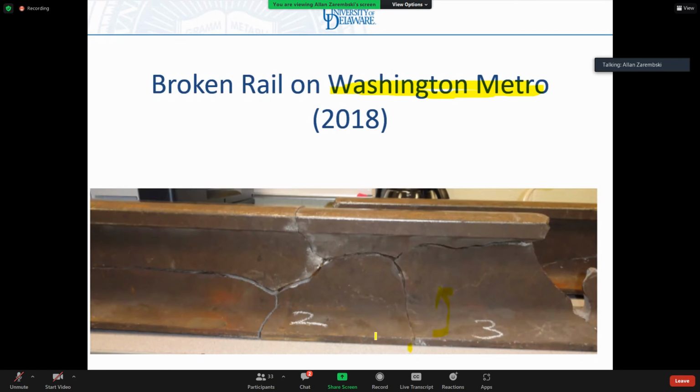Remember, I keep giving you all this esoteric theory, because the theory actually has a meaning when we start looking at failure mechanisms. So because we had a stress riser in the base of the rail, there was a crack that initiated. Actually, I believe it started over here, sorry. It initiated over here, went through here, propagated through here, came down here, propagated through there, propagated up there, fractured the rail and under the train. And fortunately, there were no fatalities, only injuries that went to the hospital.